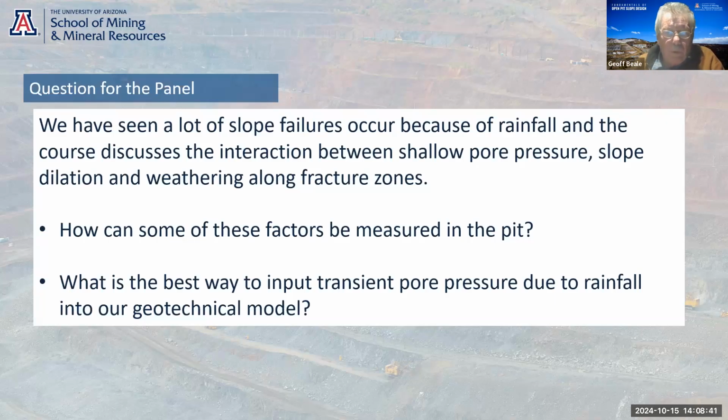Well, I think more and more, and Jim Weigel can jump in on this, there's a couple of parts to it. Firstly, we're putting in piezometers very shallow. So at a lot of sites we're putting in 50-meter holes and putting pressure sensors at 50, 40, 30, 20, 10 meters in the hole. So we actually start to measure the way water goes through the shallow part of the slope. Those piezometers can be focused. Obviously, there are some sectors of the pit which are more susceptible than others. So focus them where you think there are issues, but shallow piezometers.